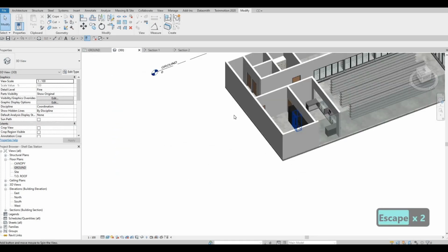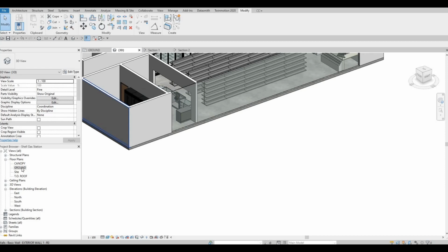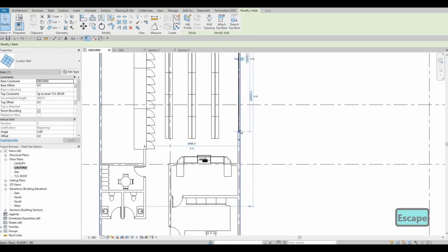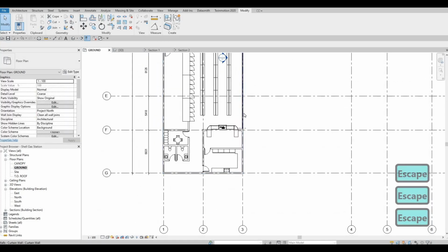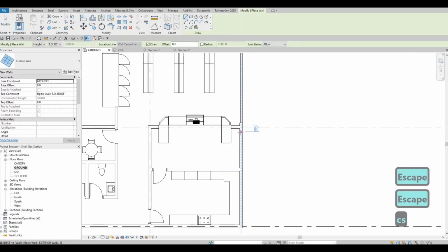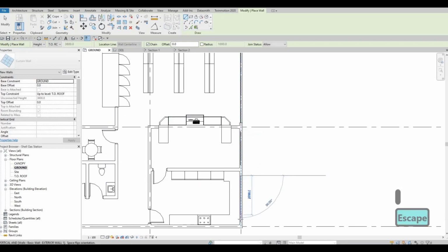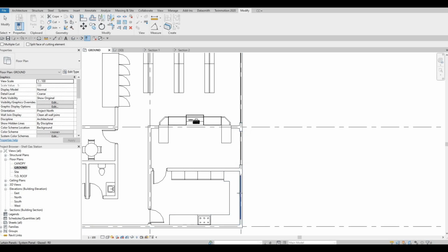and obviously we need to pull it up a little bit. What I'm gonna do actually is to single out everything. That means that I'm going to add a curtain wall right here and then a different curtain wall onto this area because it has different heights and I don't want to put everything on a single height. So that's why I'm gonna do this. Cut geometry right there and then cut geometry right here.